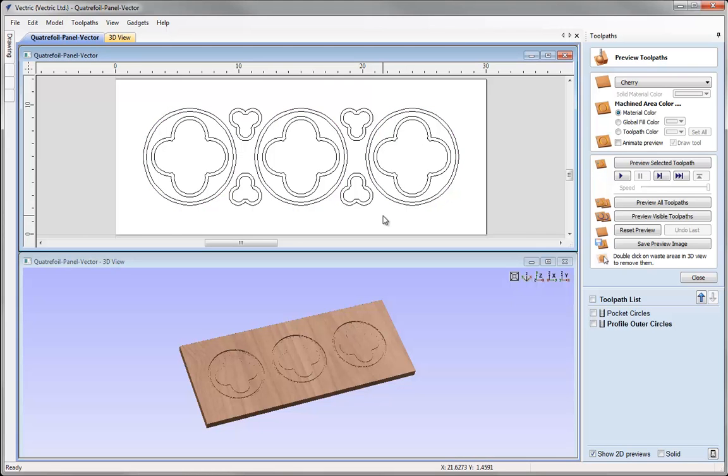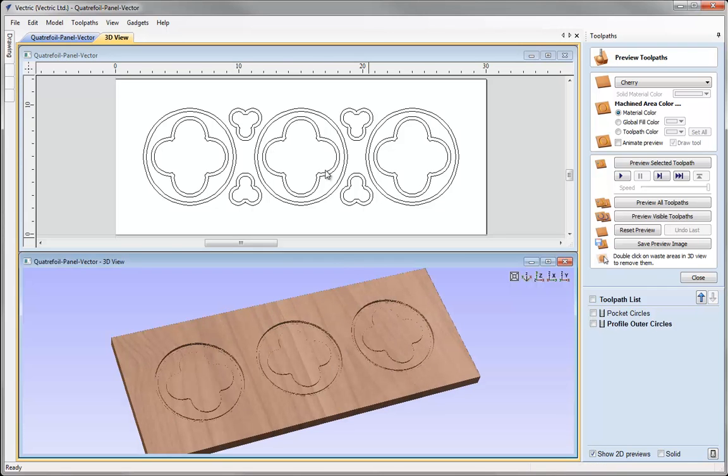And for both of these, quatrefoils and trifoils, we're going to be using a 1/2 inch ball nose tool. Now it'd be nice to actually be able to do the quatrefoils and trifoils all in the same toolpath. But we need to remember that our quatrefoil shapes are going to be sitting in this centre circle here. Now we've already machined down an 1/8 of an inch here, whereas our trifoils will be machined down from the top of the material. So even though we want to machine down a 1/4 inch, we need to make sure that the actual quatrefoils go down a further 1/8 of an inch.